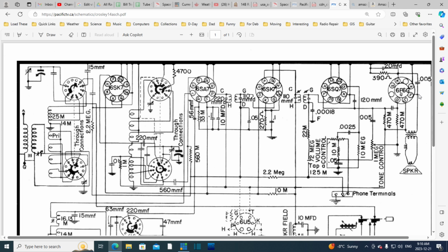Its job is to quell any harmonic signals that are coming out at very high frequency, maybe beyond our hearing even. And it's there to catch them. What happens if that's not working? I don't know, to be honest with you. It's a very small capacitor. It's not doing a lot. It's aimed, I guess, for the highest frequencies. Let's do that one. It's a 0.005. It's within range of my decade box and whatnot. Okay, that's the guy. We'll do this one next. I think it's pretty inconsequential. I need to cut it out. You wouldn't even know it's not there, I think.